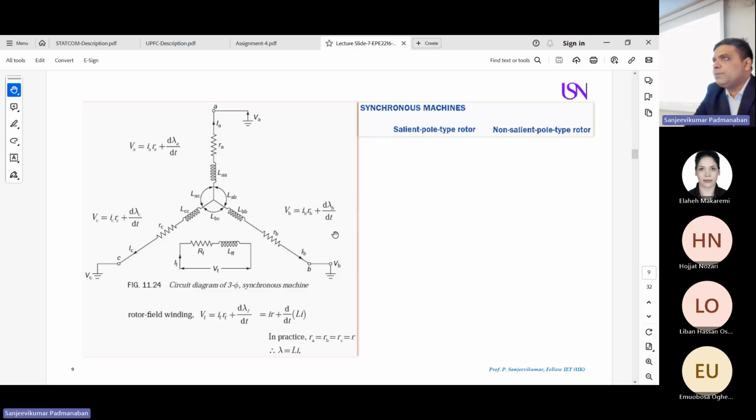So we finished the speed governor part in a very simplified equation. Please note it is a first order system, an exponentially increasing function, a low pass filter. We made the complete speed governor system of your hydropower plant into a first order system, so the analysis becomes very easy.